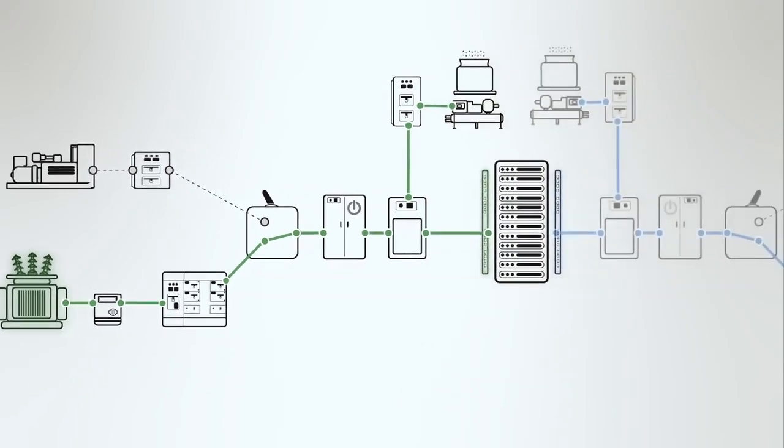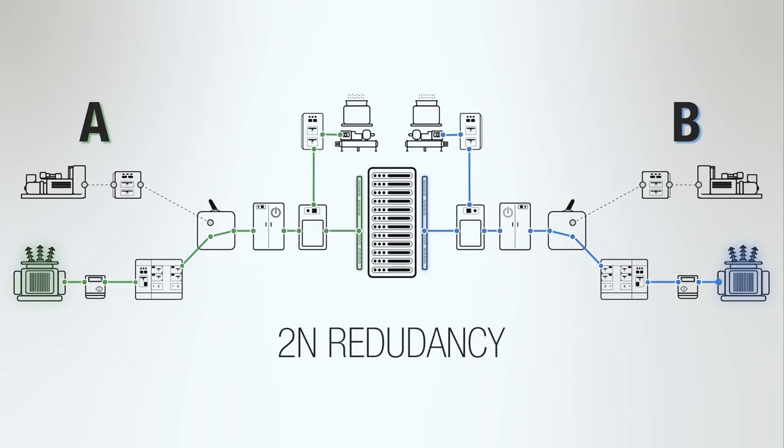Tier 3 and Tier 4 data centers require 2N redundancy, which is a mirrored system with two separate points of independent distribution, ultimately feeding two separate rack PDUs, and an AB feed that typically supplies power to A and B power supplies within the IT device for complete redundancy of power.